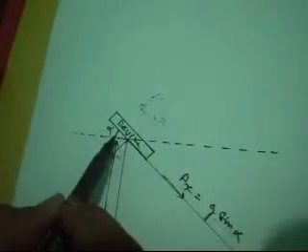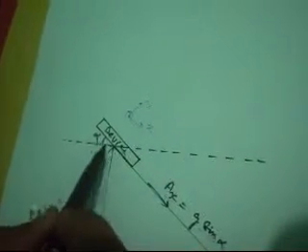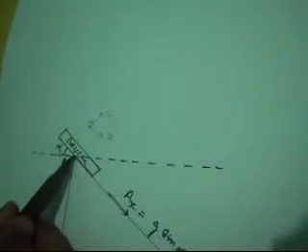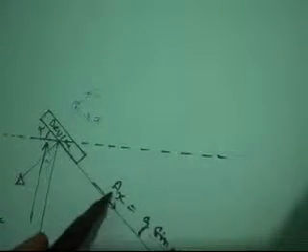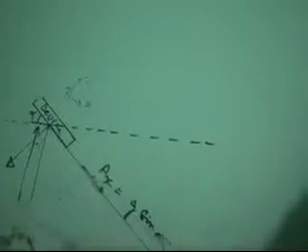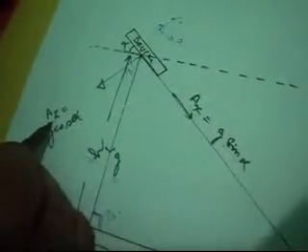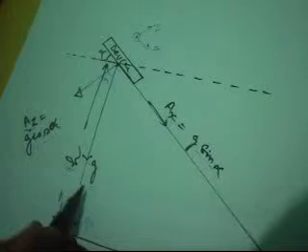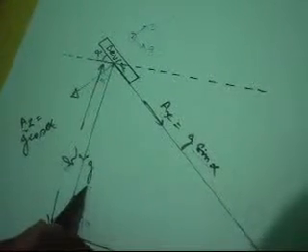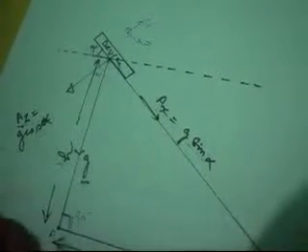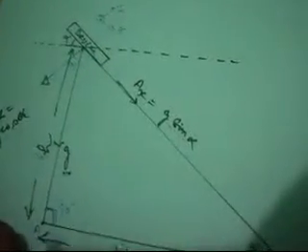Tilt angle alpha of the device with respect to the horizon is measured with the help of the accelerometer. Accelerometer can measure the acceleration along its three axes. Let the acceleration along the x-axis be ax and acceleration along the z-axis be az. The gravitational force G can be utilized to measure the tilt angle alpha.